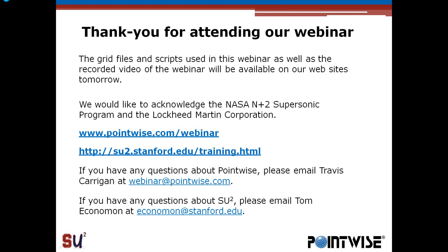Yeah, so I think if I understand the question correctly, one of the things with the continuous adjoint is you may have noticed the surface sensitivities look a little noisy. So if this is on the optimization side of things, we take that surface sensitivity map, which may look a little noisy, but we always project that into a design space of variables so that we have a smooth gradient to work with in the optimization.